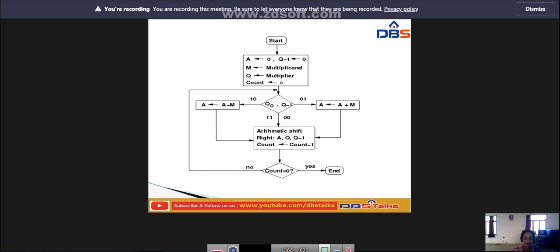The algorithm works for positive or negative multipliers in 2's complement representation. This is because a negative multiplier ends with a string of ones, and the last operation will be a subtraction in the appropriate weight.